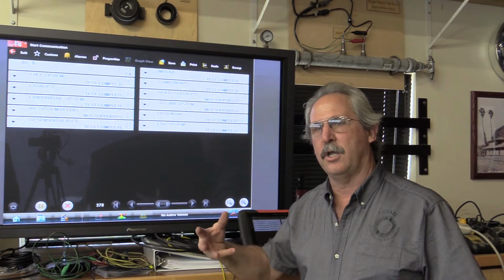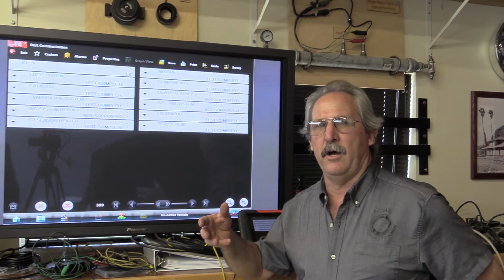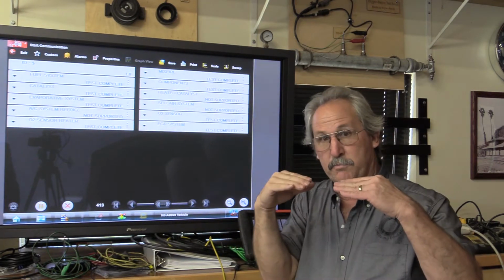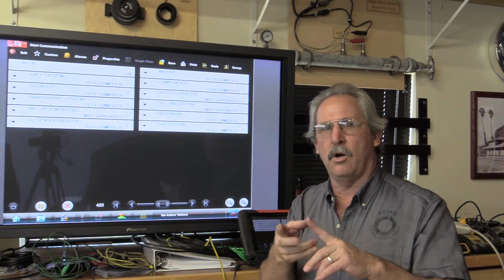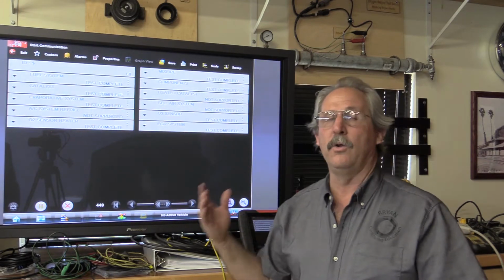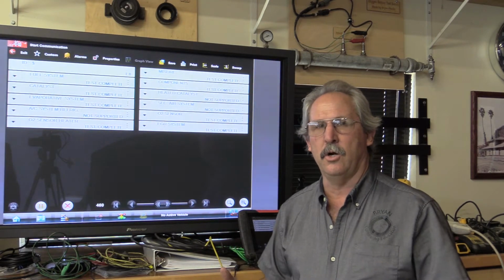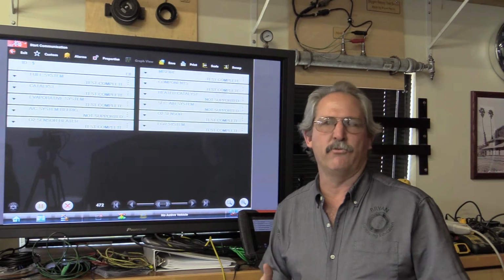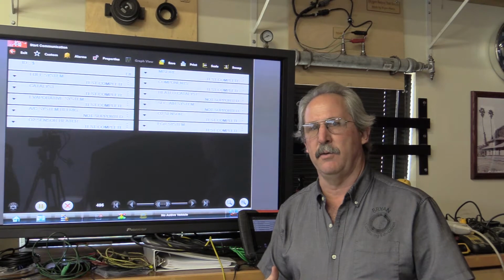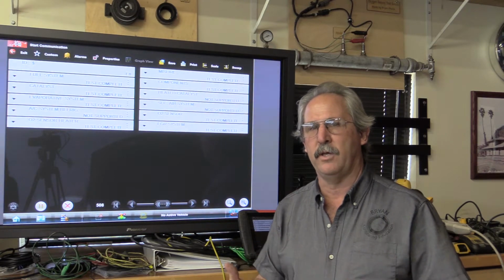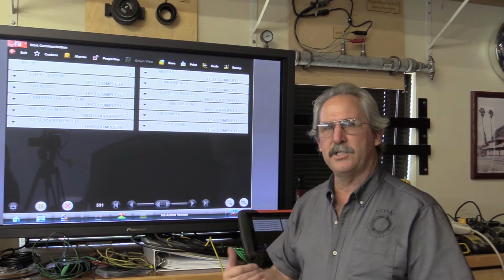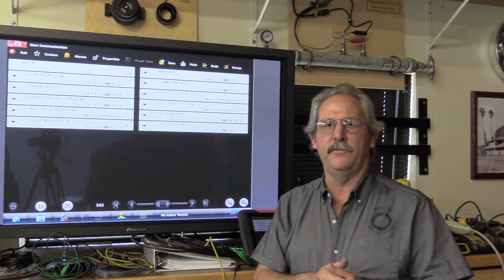And if I look at the documentation from the Society of Automotive Engineers, it'll tell me that this space in the computer can either be EGR or VVT. The issue we have is the software and the scan tool only understands it's EGR. Our scan tool is kind of like an address book. So our addresses in OBD2 are all based on a hexadecimal numbering system, and the scan tool goes to different locations thinking it knows who lives there. So as far as my scan tool is concerned, EGR is who lives at this address.